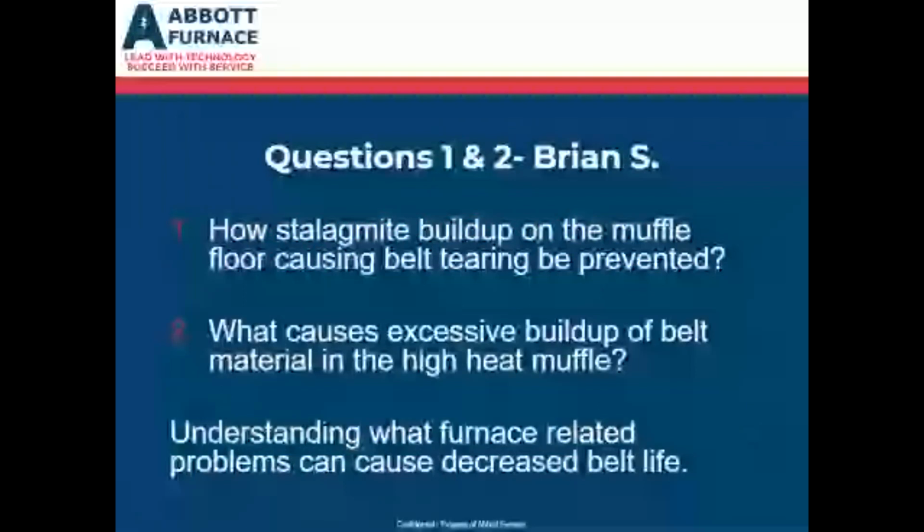Anyone that's familiar with powder metal will know that we add lubricant to the powder for compressibility. And then in the sintering stage, we have to remove that lubricant through the preheat zone in the furnace. If that lubricant is not completely flushed from the furnace by the atmosphere when it comes out of the parts, it will decompose into carbon.